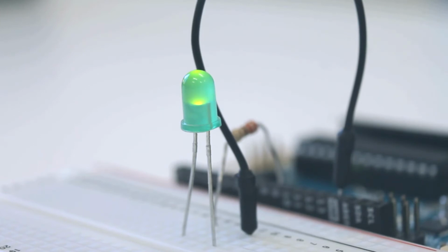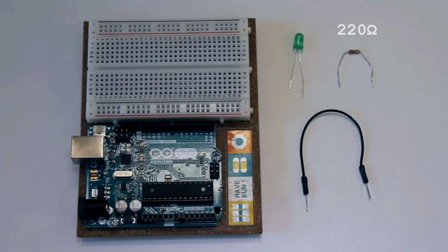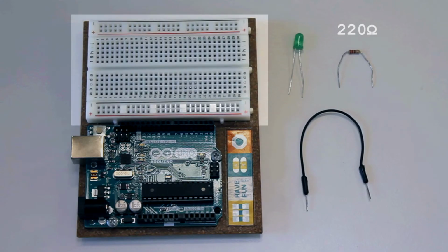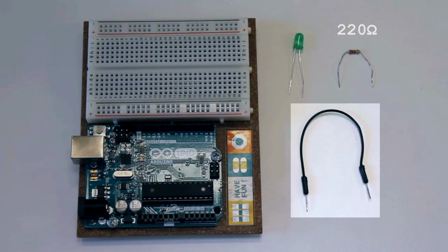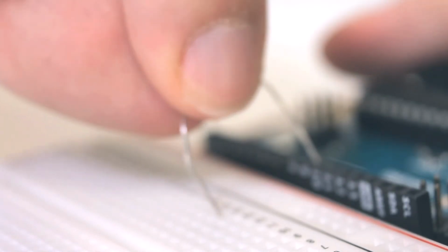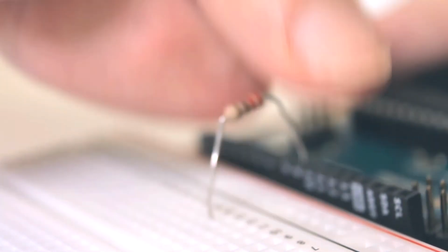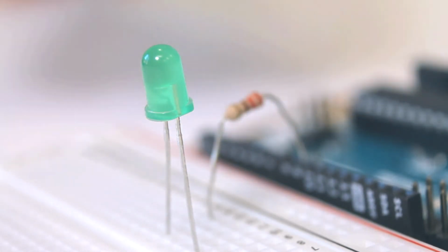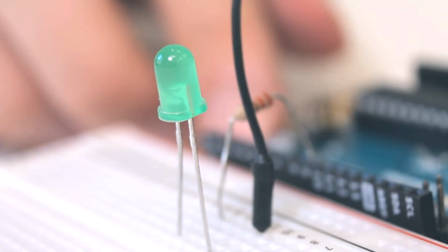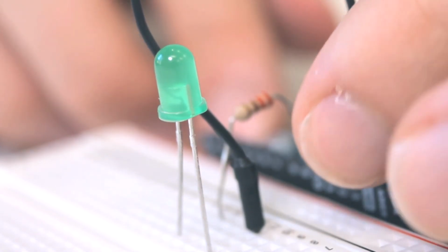We will now demonstrate a blinking and fading LED by using both digital write and analog write functions. To follow along, you will need an Arduino, a breadboard, an LED, a 220 ohm resistor, and some hookup wires. First, connect the used PWM pin to the resistor. Here we are using pin 9. Then connect the longer positive leg of the LED to the resistor and the shorter leg to ground.